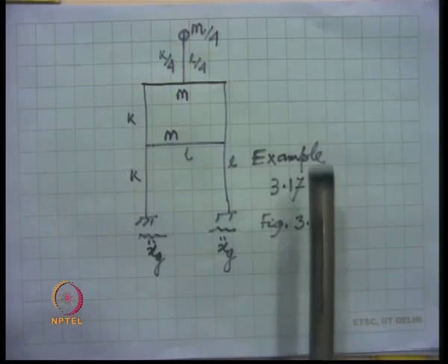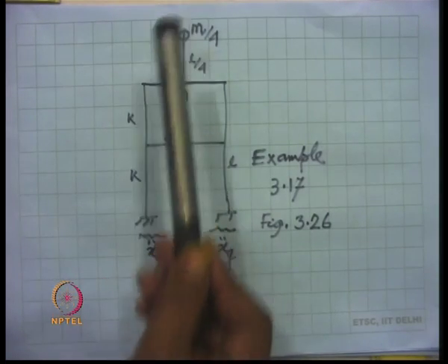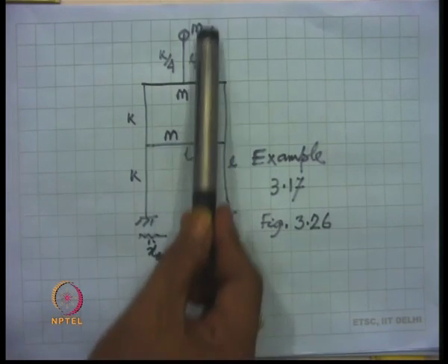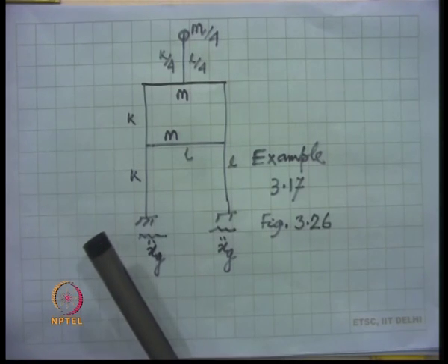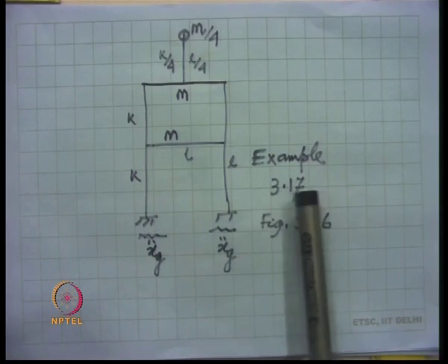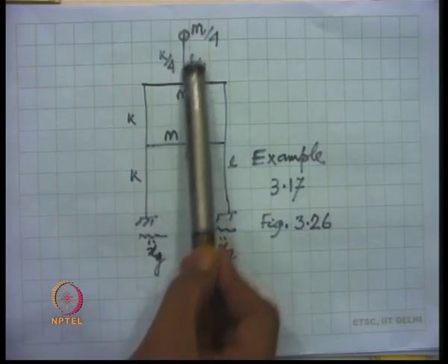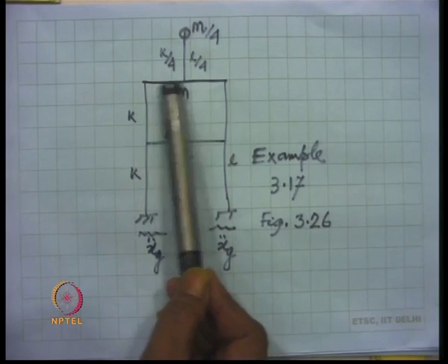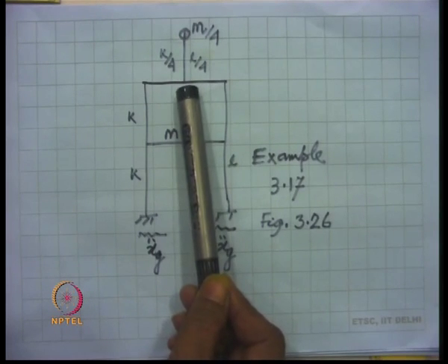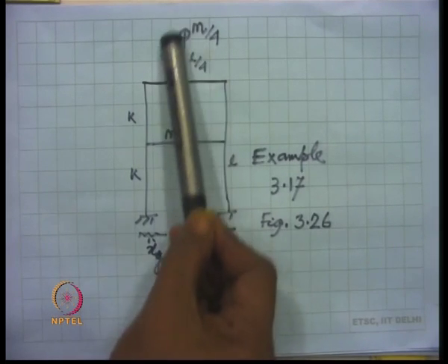These response spectra are now obtained for the required damping, and in this case the damping is 2% because the secondary system has a damping of 2%. So, once we have the response spectrum of acceleration for 2% damping, then for this secondary system an excitation record acts at the base of the support, whose response spectrum is now known, and therefore the time period for this secondary system